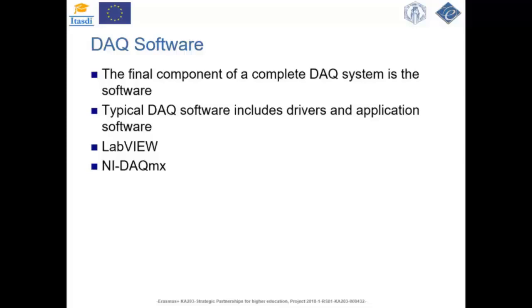The software also controls the data acquisition system by controlling the DAC device and specifying when and from which channels to acquire data. The DAC software thus acts as a single programming interface for programming the analog input, output, digital input and output, and counters or timers on hundreds of multifunction data acquisition hardware devices.